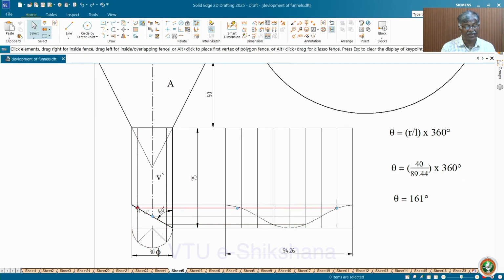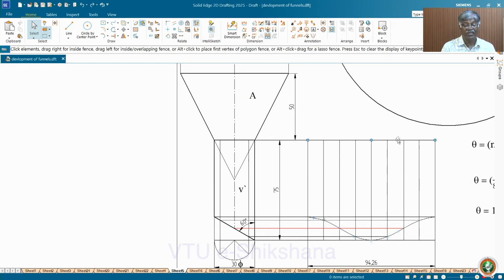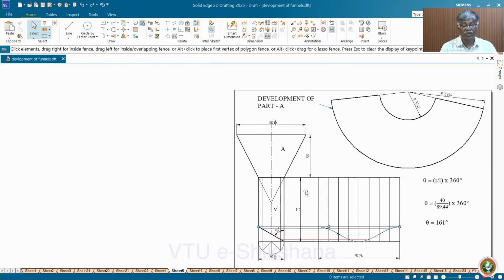After selecting the section plane, you choose the section points and then project onto the respective generators. You can name 1, 2, 3, 4, and then corresponding points A, B, C, D. Otherwise, you can do as such. There is no need to name all this. Just mark, but better to name for clarity, if space is available and this is legible.